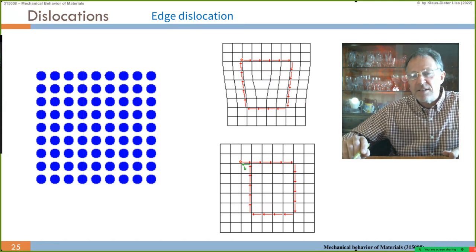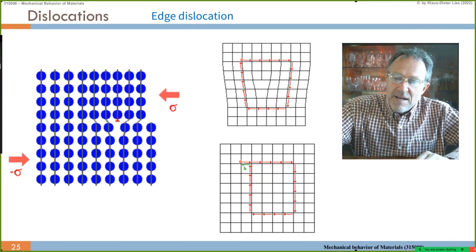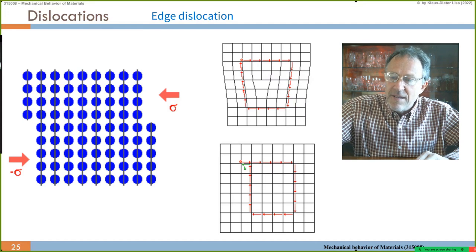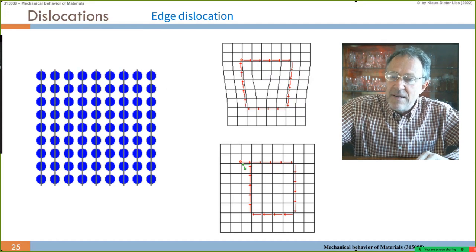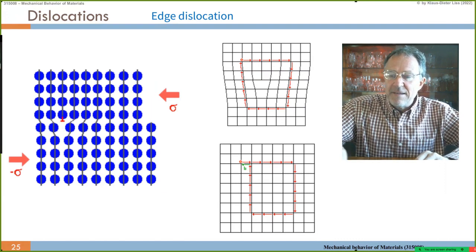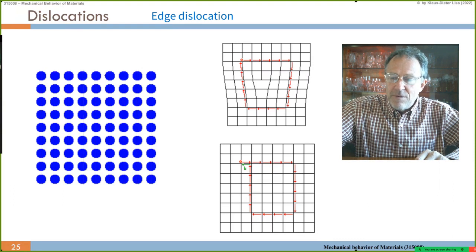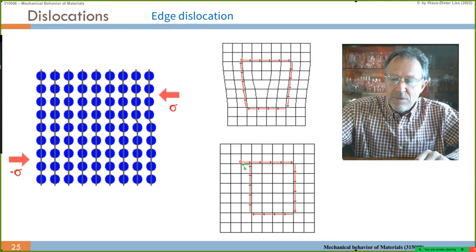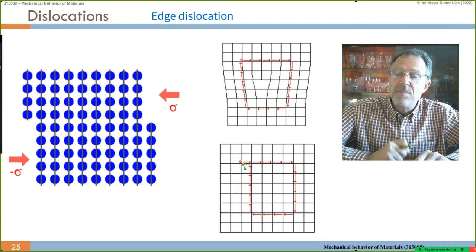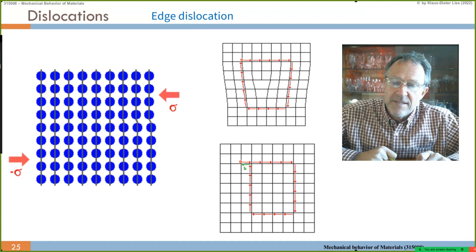How do we find the dislocation? Well, we start at a point in the lattice, and then we go 1, 2, 3, n steps in one direction and m steps in the other direction, and then we get the n steps back. So n is 3 here in the horizontal, and 1, 2, 3, 4, 5 up, 1, 2, 3, 4, 5 up. Then I should end up at the same position. This is in a perfect lattice where we have translation invariance.